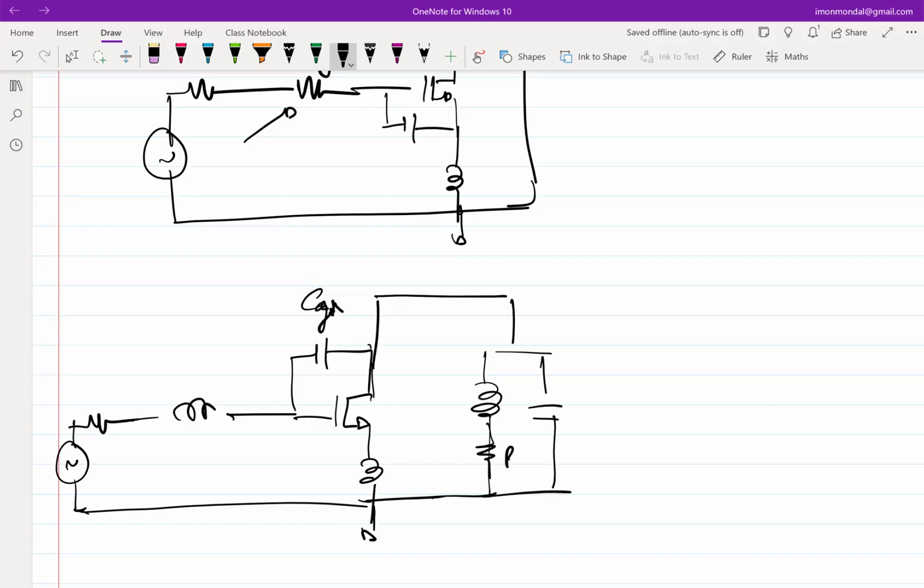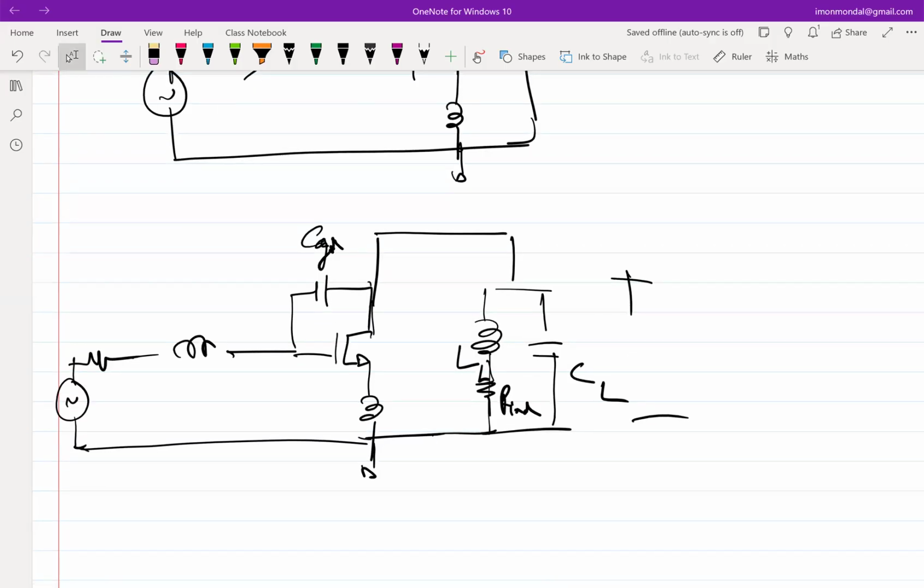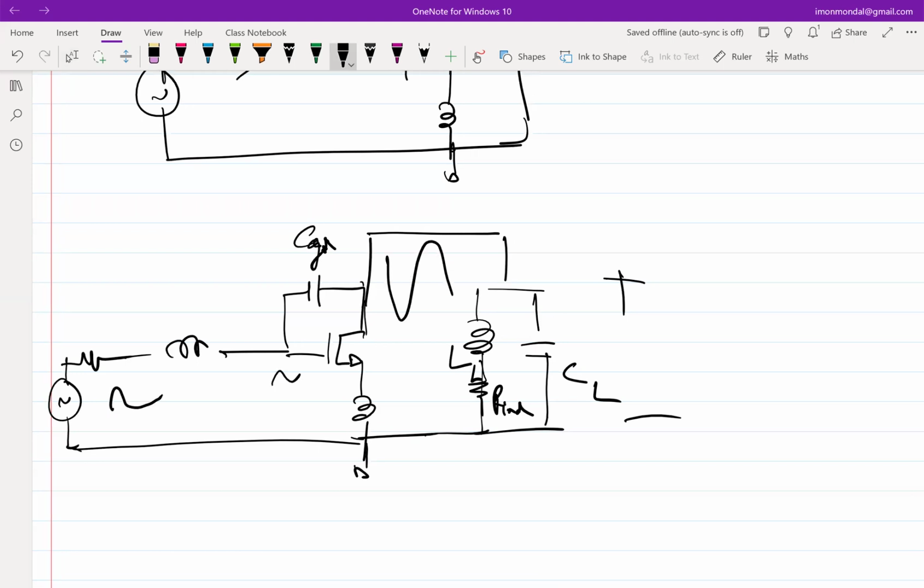And there will be a, not RS, should be R in. And this RD is going to give you some real part, and you essentially get a output because of that, right? So this also helps in reducing noise. If you put an explicit resistor, you will lose headroom, you will increase noise, all those things are going to happen, right? So the issue now is this: if input swings, this guy is going to swing much more